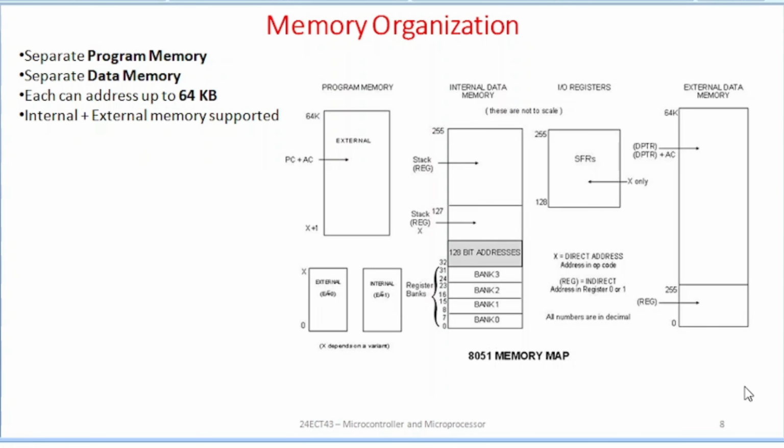The program memory area, that is EEPROM or flash memory, is used to store extremely large amounts of information and never loses it when the power is removed. Program memory is used for information needed each time power is applied, such as initialization of values, calibration of data, keyboard lookup tables, etc., along with the program itself.